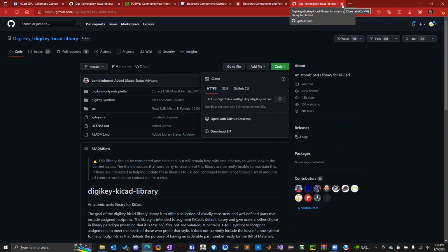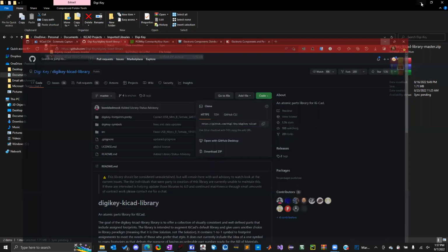the symbols if you don't have to, because it takes a lot of time. You could make a mistake. There's a bunch of things that could go wrong. With the symbol, it's a little bit easier, but for the footprint, you definitely want to try and find the footprint online. Most of them are made if it's a common component, but very rarely you should have to create one manually. We'll get to that next Wednesday. I'll talk all about the PCB layout and all the tools and stuff for KiCad.